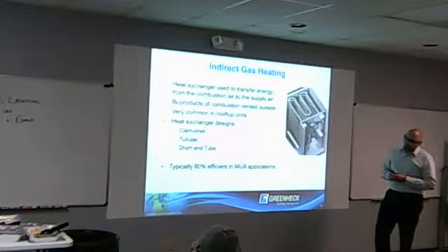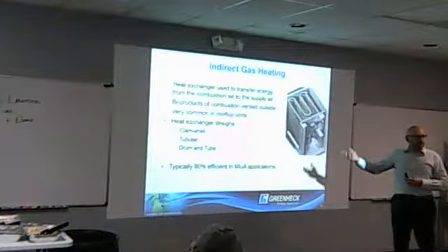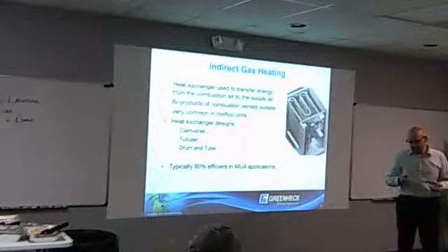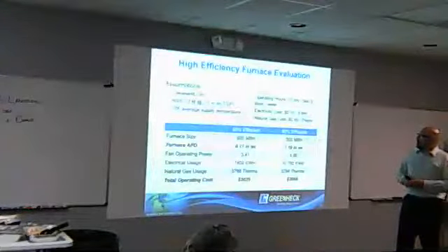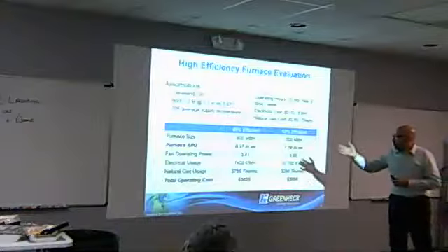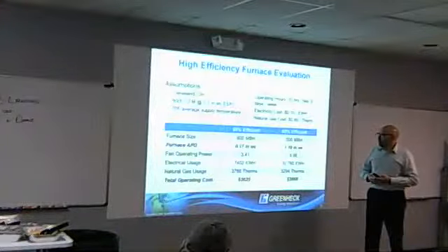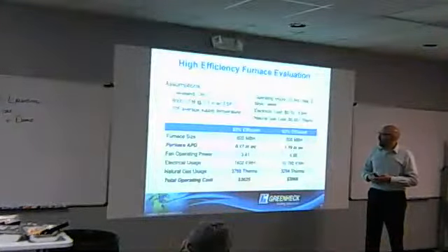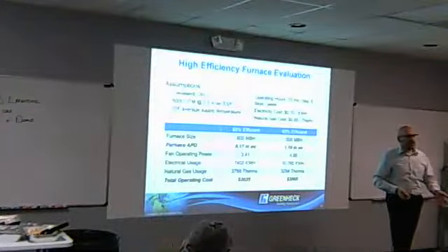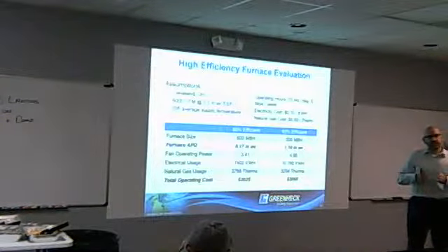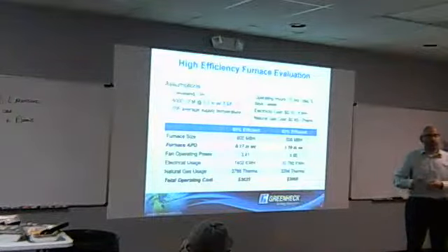So some people say, well, wait a minute, my furnace at home does 92% and it has a heat exchanger, why don't you get to 92%? Or something of that nature. So we looked at an example, and what it comes down to is return on the investment or lack thereof. If we get to 92%, usually what does that require after the primary heat exchanger? A secondary heat exchanger, higher condensing. So you have two challenges.